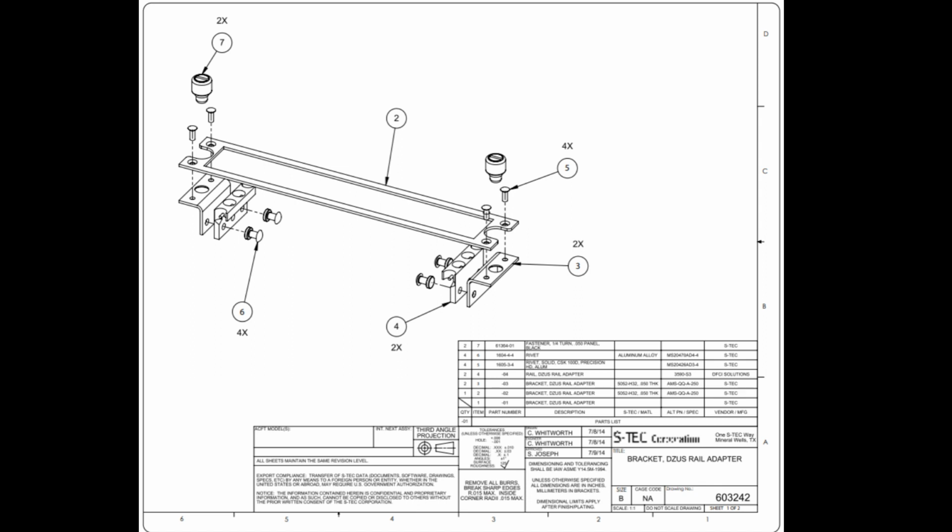To complete the reading of a drawing, read the general notes and the content of the material block, find the various changes incorporated, and read the special information given in or near views and sections. End of page 4-21.